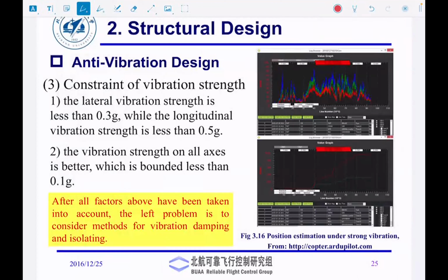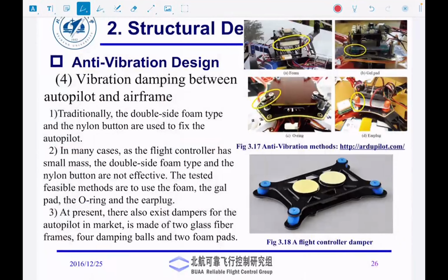Typically, when you do some sort of wind tunnel testing on an aircraft, you get a vibration signature. You characterize the overall vibration and then use some type of filtering to minimize those vibrations so that the navigation data you get from the navigation computer or IMU is meaningful. There are different isolator techniques, all the way from foam pads and rubber bushings to elastic bands for small aircraft. For large aircraft, there are dampers.